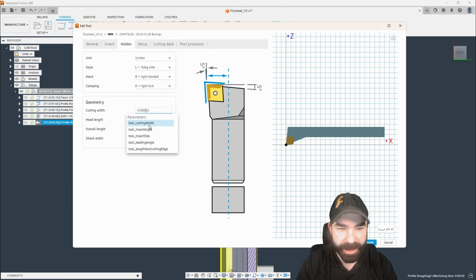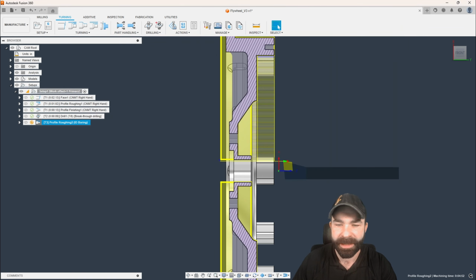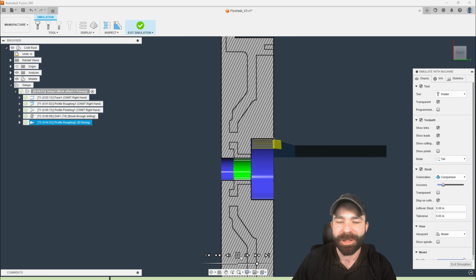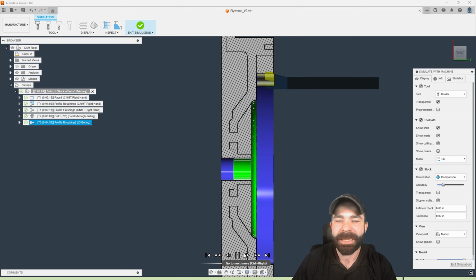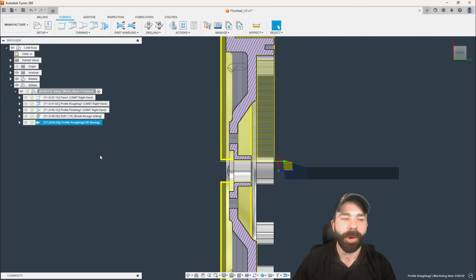And again, for this video concept, guys, a lot of this stuff is built around giving you the ability to use the CAM cycles to do this, more than it is the exact and precise increments that you need, at the end of the day. As you've noticed, I haven't adjusted my step over, things of that nature. Those are all tool parameters that you're going to change. So again, based on the fact that we have now simulated that with a different offsetted boring bar, we have made this with no problems, no collisions, and no issues. So I'm very happy with this roughing strategy.